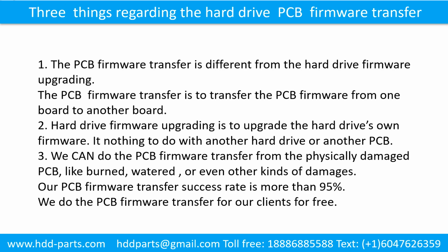3 things regarding the hard drive printed circuit board firmware transfer. 1. The printed circuit board firmware transfer is different from the hard drive firmware upgrading. The printed circuit board firmware transfer is to transfer the printed circuit board firmware from one board to another board. 2. Hard drive firmware upgrading is to upgrade the hard drive's own firmware.